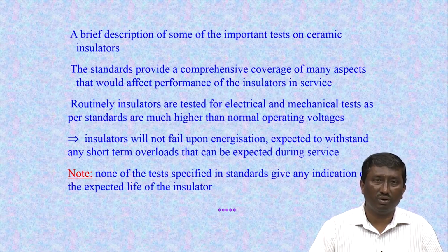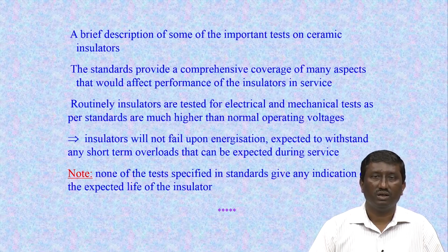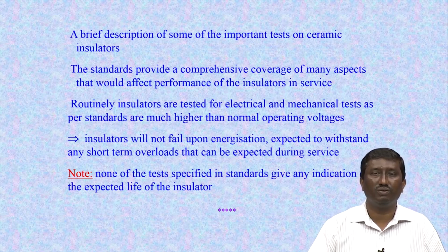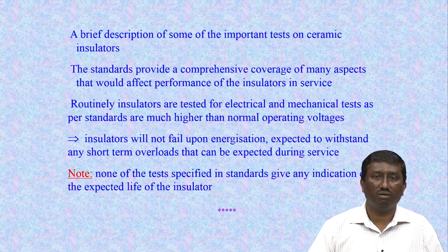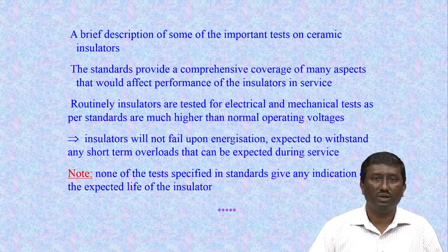The tests for reliability have to be carried out before installation in the field, but a note is to be made that none of the reliability tests which have been discussed, specified in the standards or in the technical reports which are internationally followed, give any indication of the expected life of an insulator after performing these tests. So, the utilities and the manufacturers have to weigh the options, which technology or which type of insulator to be used, and then it has to be decided. Just by performing the entire test, there is no guarantee that the insulator string will last for its expected life, as there is no indication of life expectancy of the string in the field from these lab tests. It should be noted.